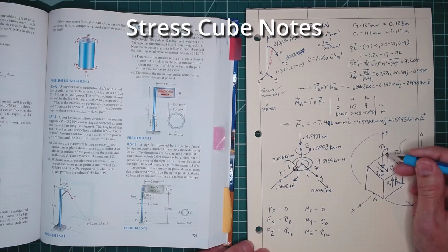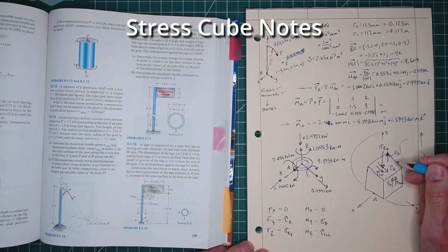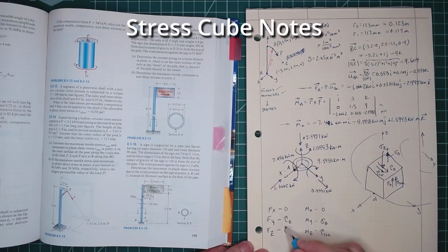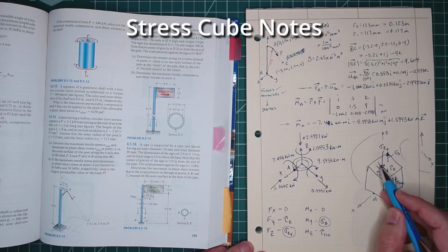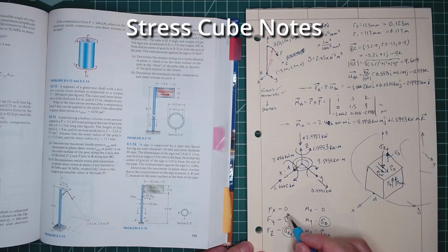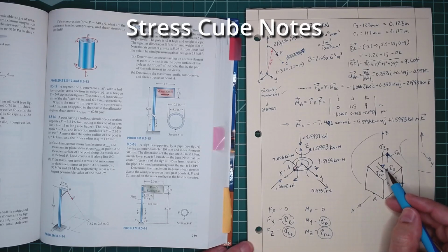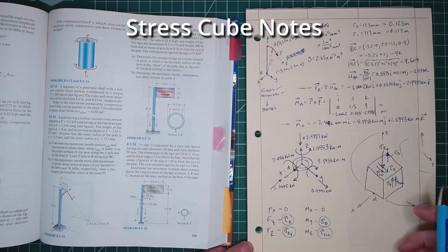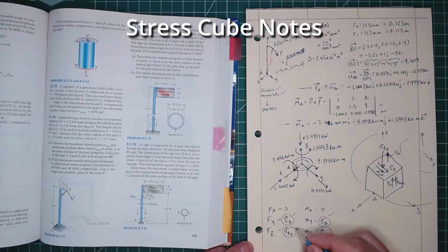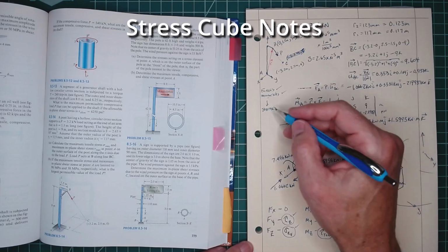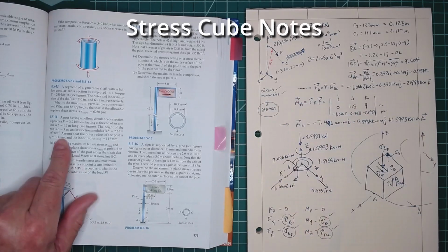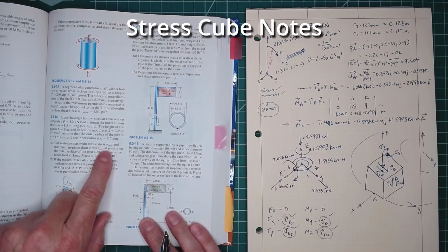We've got two axial forces acting on this top face, our sigma ZF and our sigma B. And then for shear stress, in this direction, we have two stresses, our tau B and our tau due to a torque, acting on those two faces. The nice thing now is we know what stresses we need to solve for. That's ultimately what we need to figure out our sigma max and our tau max.